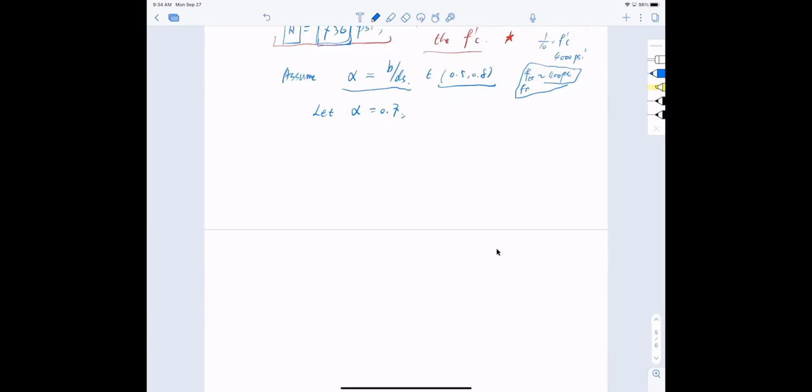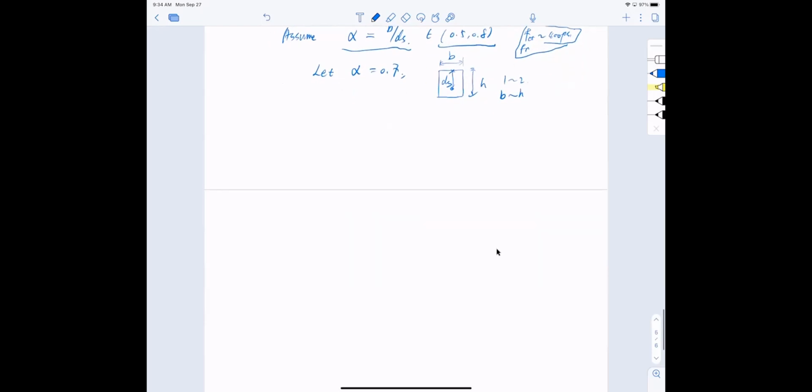It's just proportional in my head, because if I add the height to the ds, I essentially get about 1/2 of the width. I prefer my section to have a 1:2 ratio, that means b and h have a 1:2 ratio. But b to ds, usually I get about 0.7 or 0.65 sometimes. So that's just me, okay?